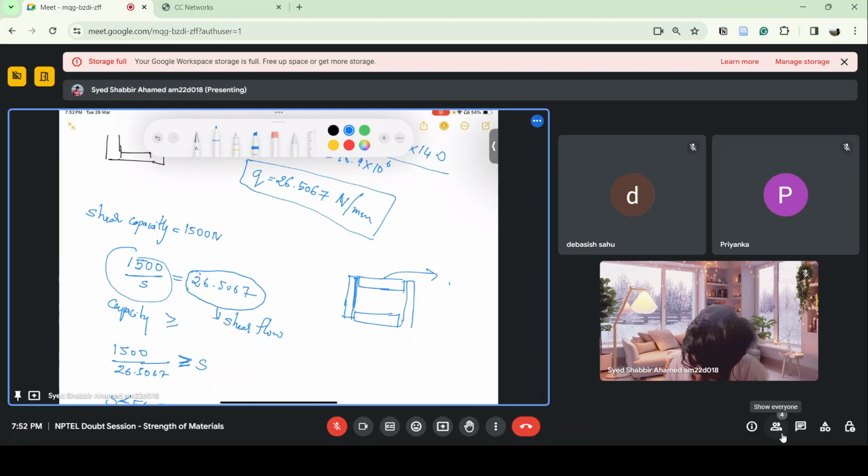For this thing, shear stress goes on increasing, but at the middle it is not maximum, and it becomes zero here. It is maximum at some point between the bottom part and the middle part. So it's better that we take more shear stress into calculation so that the nail can resist better.